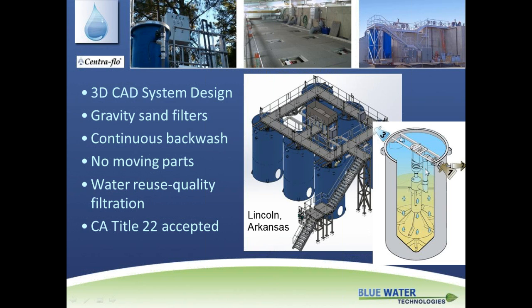It enters through a pipe network or a central assembly that brings the water to the bottom of the vessel, and the water flows upward, as these arrows illustrate, to overflow a fixed effluent weir at the top of the vessel. Now, through this portion of the vessel, there's a media bed. We use a sand-based media which we coat for an absorptive uptake of metals. So again, water moves upward and overflows a fixed effluent weir.